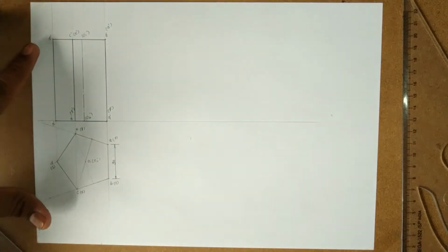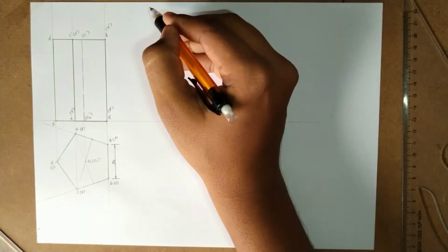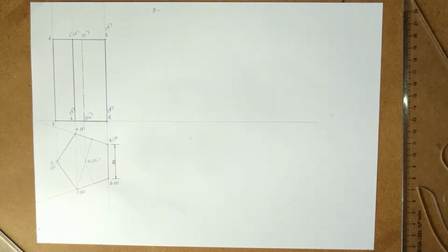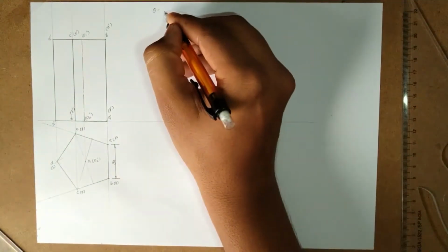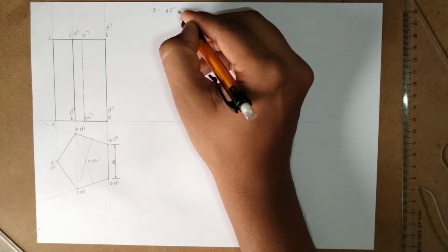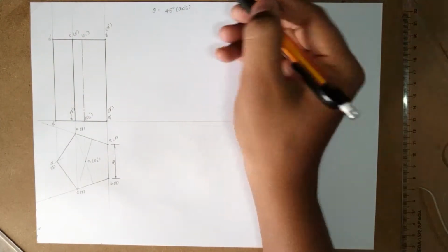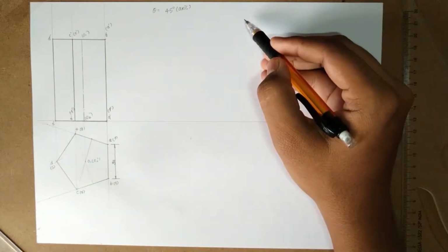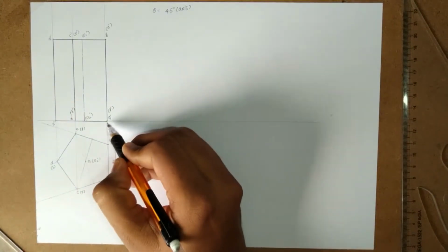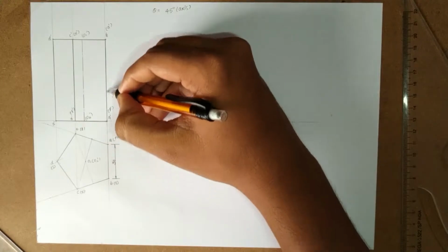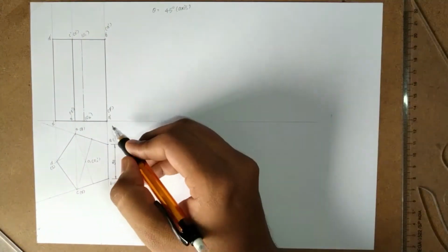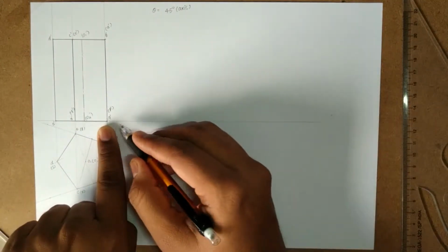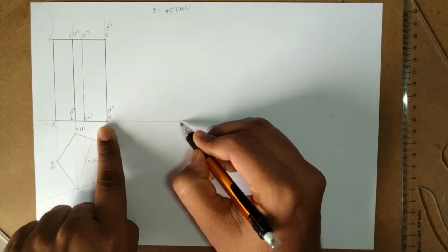as the object is resting on HP, we need to take the inclination with HP first. So this will be theta inclination, which is already given as 45 degrees. Okay, so this is the 45 degree inclination with the axis. I will try to make this axis inclined at 45 degrees in this case, but it is preferable to move this vertical line to 45 degrees, because I need to keep this point on the base. Okay, so I will just make this particular point over here,